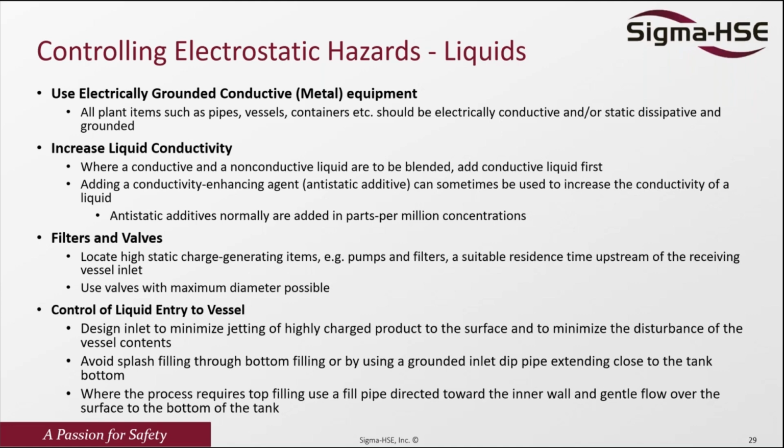Sometimes in case you are filling, you don't need to just drop from the top to the bottom, otherwise it is going to splash on the bottom, which is going to generate charges. Also in the process of filling, it's always better if you can drop it to the bottom so that it will not have any kind of splash, and this can control static discharge during filling or emptying of any liquid material.